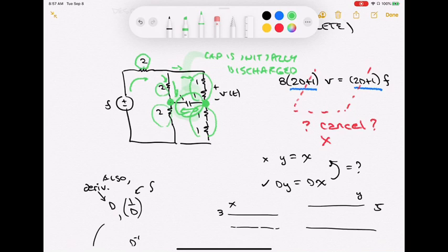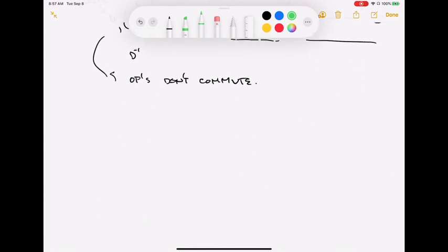This is one of those weird cases where, if you have that capacitor initially discharged, in the 0 state, and you prod it from the input side, you would never be able to see that capacitor, because the load would always appear balanced and a voltage would never be brought onto that capacitor. It couldn't happen. So from an external view, we can never see that capacitor. What we see is something that looks more like this. You have an F going through a 2 ohm resistor, and then it ends up going into something that looks like this balanced load.